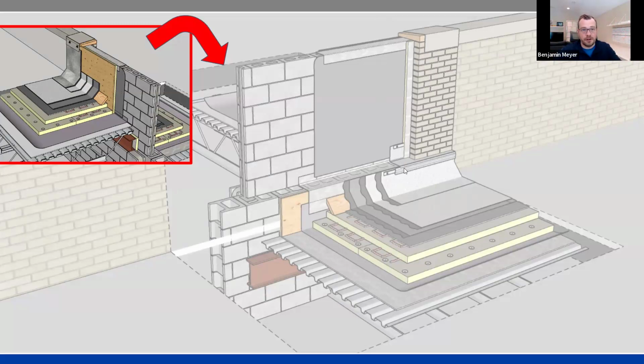One important feature to note is that this is a two-piece flashing that terminates the roof. I always joke that they could have saved probably $100 by making that a single piece of flashing, but it would make it really hard to change their roof out in the future. So the fact that it's two-piece flashing lets them have a continuous through-wall flashing, but also gives them access to maintain their roof into the future. So the little things can make a big difference.